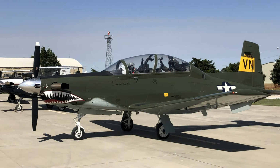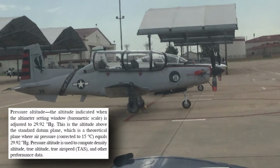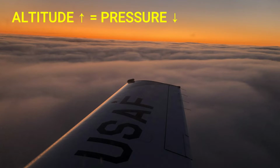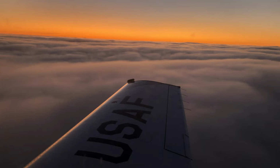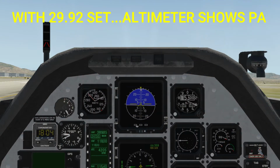In several of the TOLD charts, we'll need to know the pressure altitude. Pressure altitude is important as a basis for determining engine performance. Pressure altitude is the height above a standard datum plane, which is a theoretical level where the weight of the atmosphere is 29.92 inches of mercury. Air is denser at sea level than aloft. As altitude increases, atmospheric pressure decreases. This difference in pressure at various levels causes the altimeter to indicate changes in altitude. When the aircraft altimeter is set to 29.92, the altitude indicated is the pressure altitude.